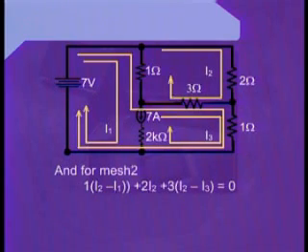These currents are current I2 due to the mesh 2 and the current I3 due to the mesh 3. However, we can see that these two currents are also flowing in opposite directions. And because we are concentrating onto the mesh number 2, therefore, while taking out the net current flow through this resistance, we must write the term I2 at the first place and subtract the current I3 from it.